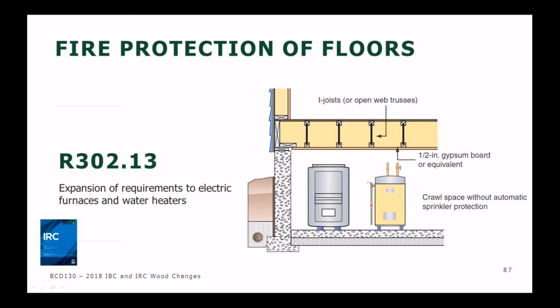All right, so I think we have time for one more, and I'm going to ask you, Sandra, to once again clarify the deck loading provisions, because we talk about residential decks here in the IRC, and folks are wondering if we apply that 1.5 factor to residential decks. Yeah, this time you do not apply the 1.5 factor for residential decks.